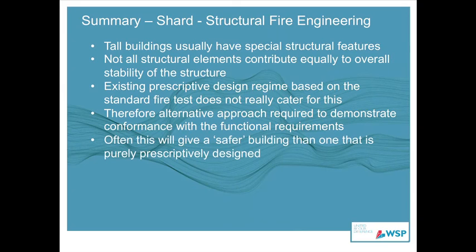Often this will give rise to a safer building, safer in that you're taking into account the critical elements of structure, and safer in the fact that sometimes you can provide enhanced measures to things like the slab, which are applying compartmentation, by identifying areas of high strain and providing additional reinforcement, which you maybe would not do in a prescriptive design.